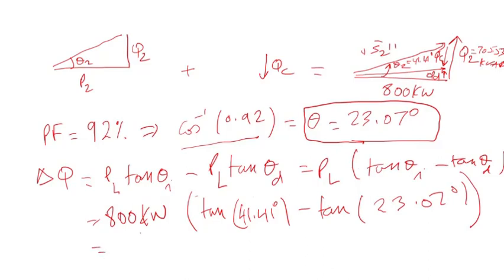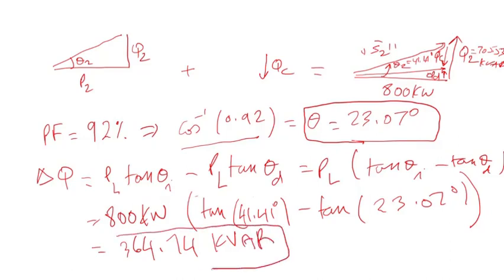If you calculate that, you will get 364.74 kVAR. So that is the reactive power that the capacitor bank needs to provide.